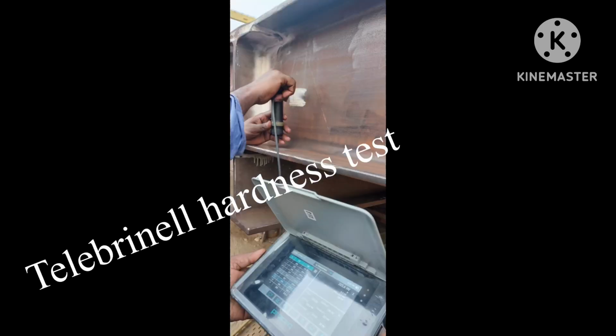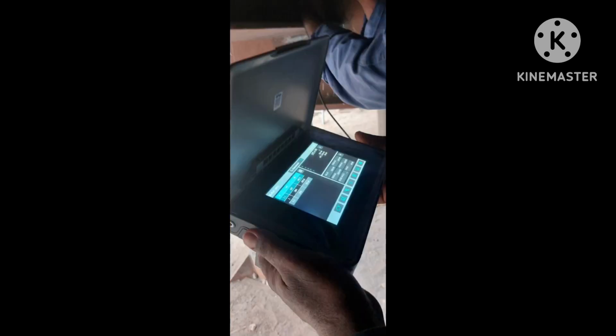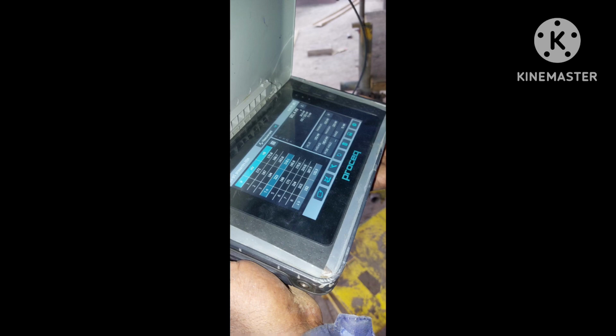First we use a block to calibrate the hardness tester. Then, it is the digital one, and we use it to find out the hardness of the material. As per the project procedure, we randomly test the hardness of the material, or of the weld material and heat affected zone, and check the hardness value.